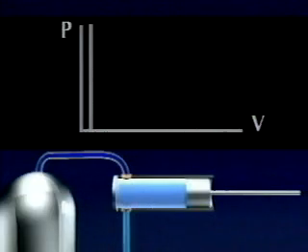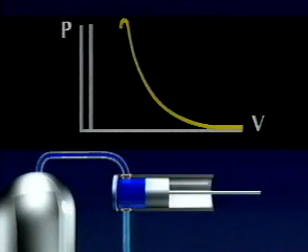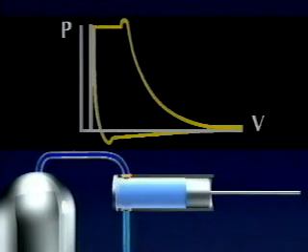This clearance determines the mechanical efficiency of the compressor. A bottom inlet port and a top discharge port complete the schematic. Assume the receiver is under discharge pressure and the cylinder is filled with atmospheric air. Movement of the piston increases the cylinder pressure enough to open the discharge valve and release the compressed air. On the return stroke, compressed air in the clearance expands, and the inlet valve opens, filling the cylinder with atmospheric air.